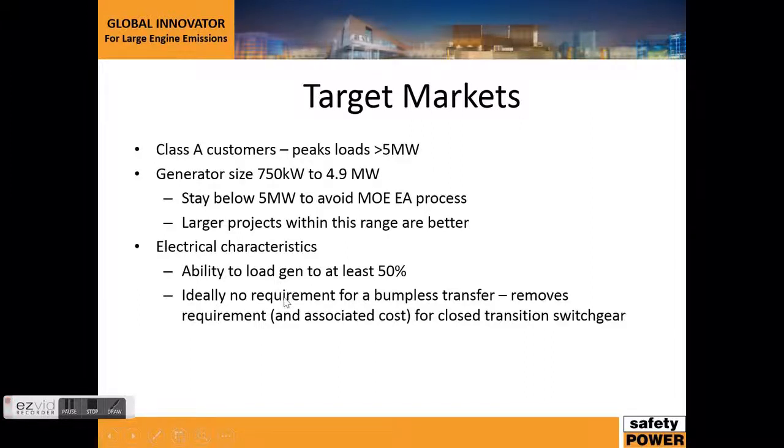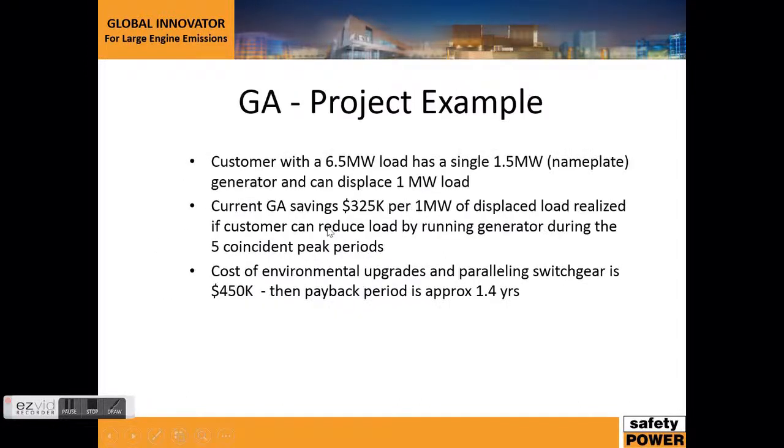Ideally, there's no requirement for a bumpless transfer. This removes the requirement for transitional switchgear, closed transition switchgear, which is an additional expense.